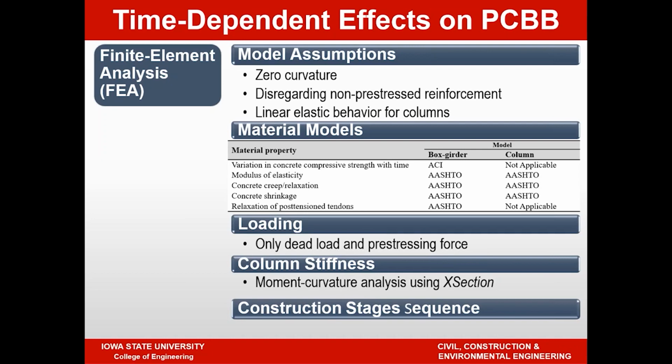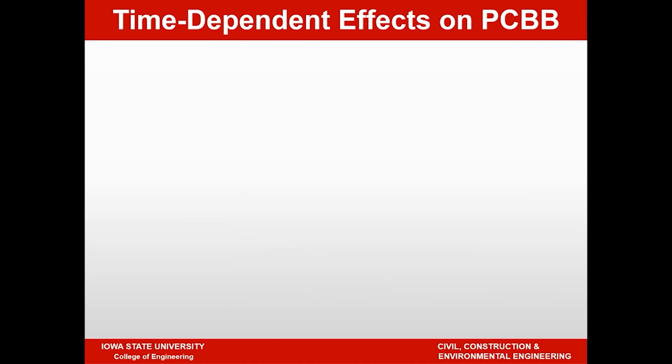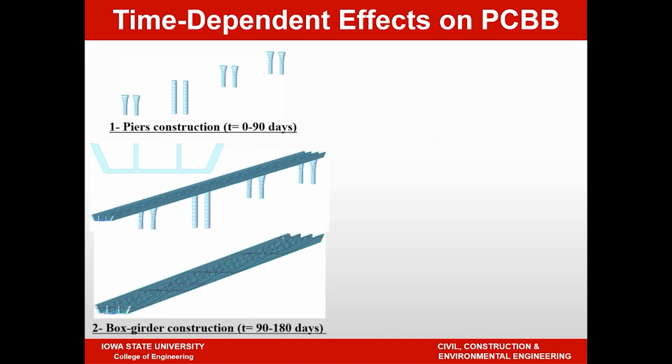The bridge goes through different construction stages, which I will show you next, and all of these construction stages were modeled in order to capture the changes in stresses and strain accurately. So this figure shows the pier construction. So typically we assumed in this case, with input from Caltrans Technical Advisory Committee, that the substructure construction